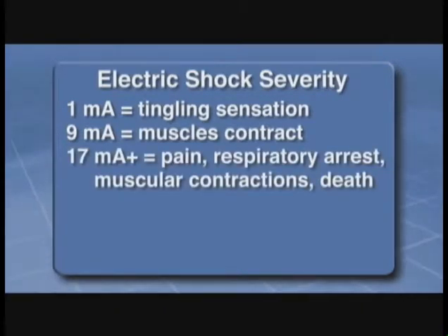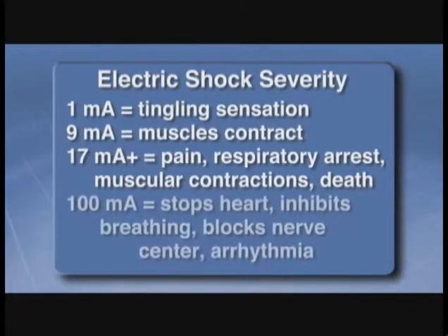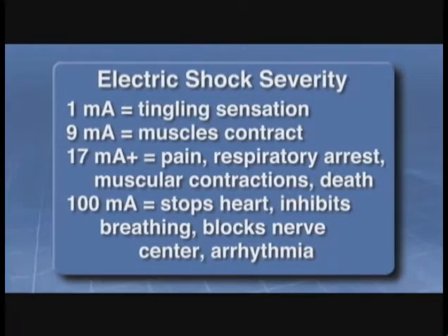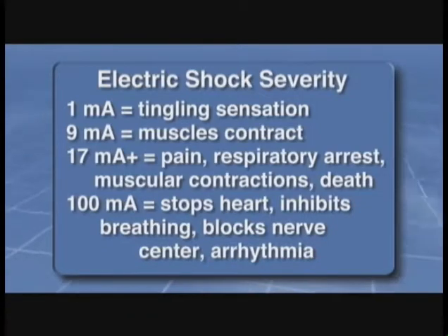17 milliamps and above can cause extreme pain, respiratory arrest, and severe muscular contractions, and in some cases, death. 100 or more milliamps are capable of stopping the heart, inhibiting breathing, and blocking the nerve center to the brain. Electrical injury can cause arrhythmia that can be fatal hours after contact.